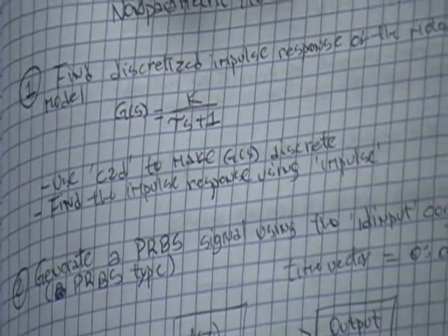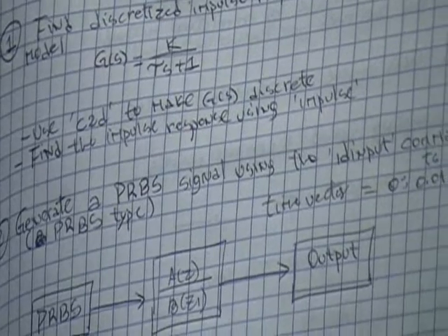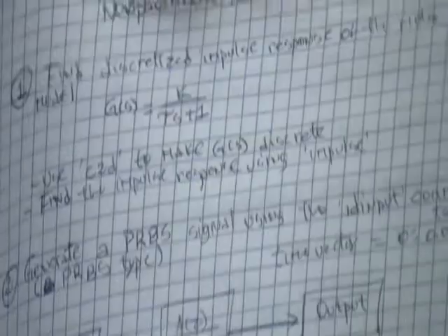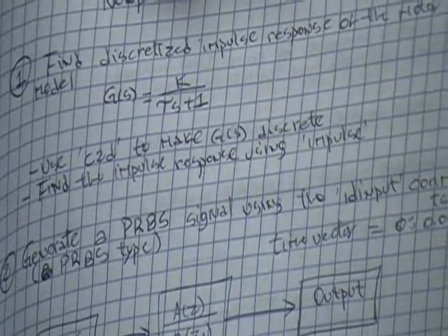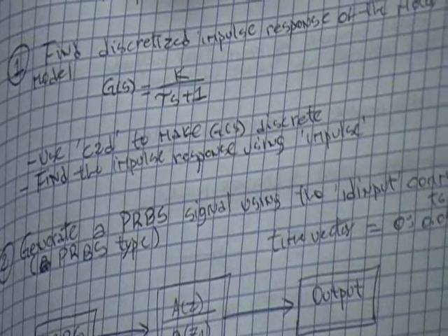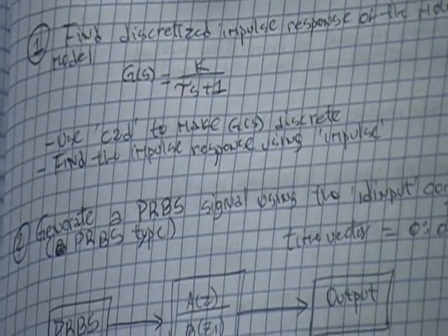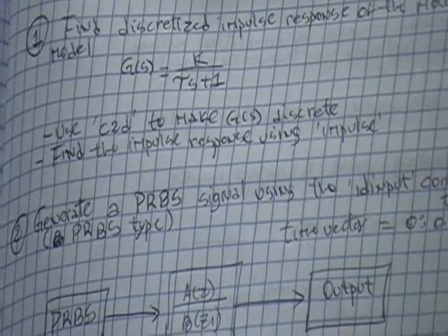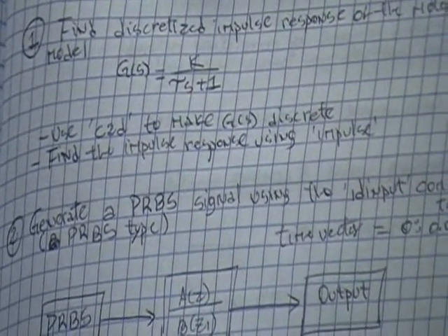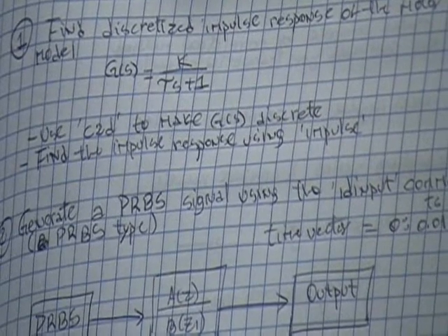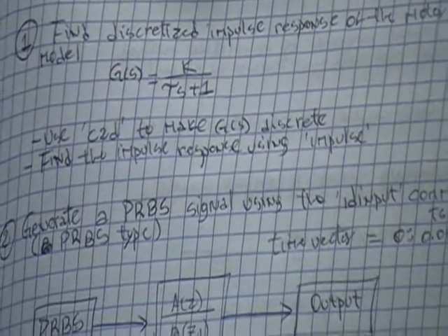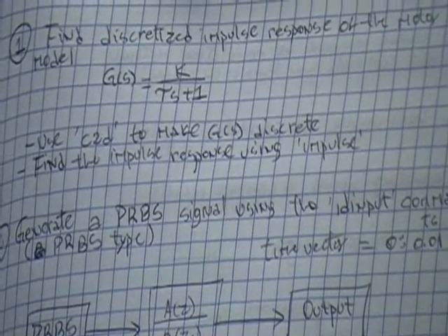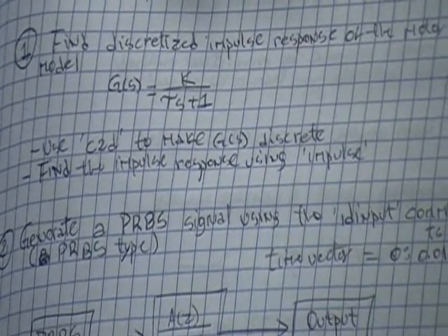Now when you specify the impulse response, it asks you for a length. Please note that in this lab we will call all lengths with capital N or big N, and big N has to always be a power of 2. So it has to be like 16 or 32 or 512 or 1024. A good number to start with for big N is around 256 to 512.